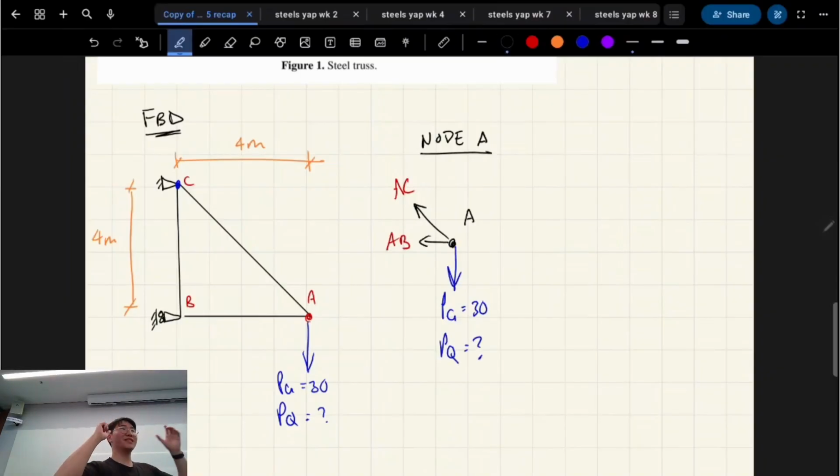Now, when we do method of joints, we basically turn this into a particle. There are no moments going on because everything's pinned. All the forces are coming off of it, no eccentricities or anything. So in this truss node, everything is only based on forces and not moments, okay? So there's no use in doing any sum of the moments, right? That's not going to get you anywhere.